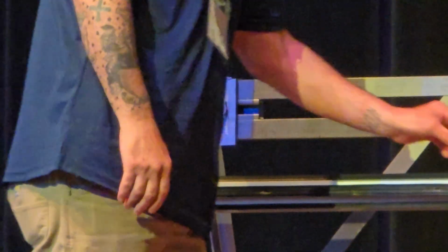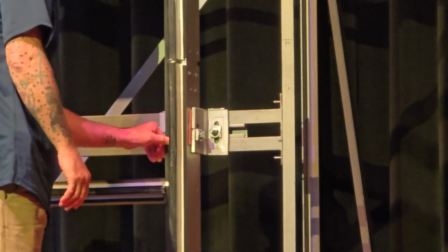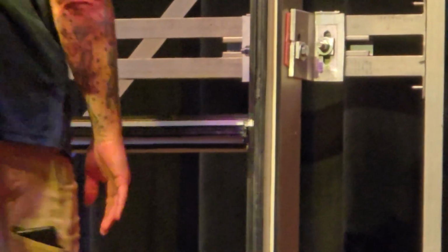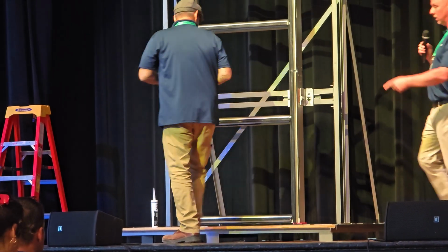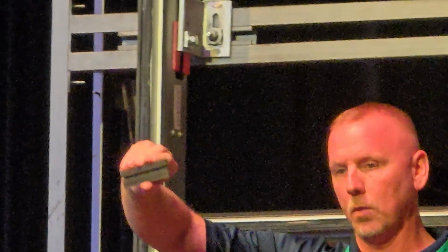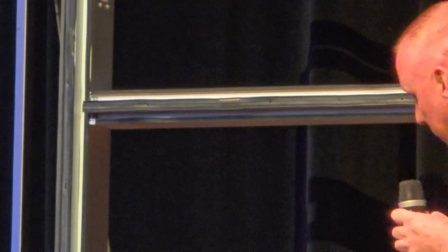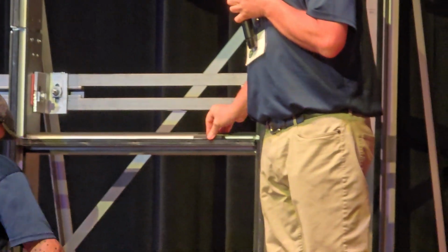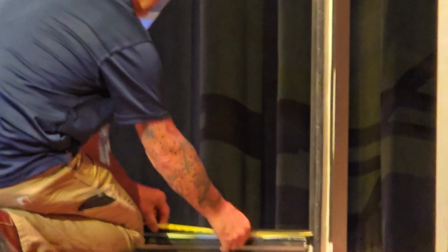Finally, the next step is, once everything is sealed, all four corners are zone dammed and caulked and sealed, you move on to the glazing process. Up here we have the setting blocks, which, if anyone can see them, have almost a channel at the bottom. They sit down, and there's also a leg on the back end that sits underneath the rubber on the back end. Those are going to be put in at quarter points for each piece of glass.